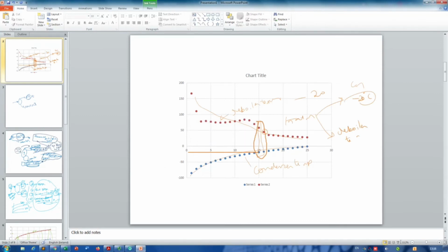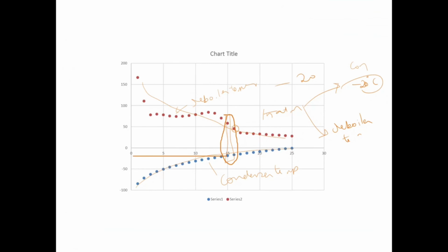And if you go back again here, I don't know where the mouse is. If you decrease the pressure to around 1 atmosphere, then you have to spend loads of energy to create a high temperature in the reboiler, and also to create a very low temperature in the condenser.